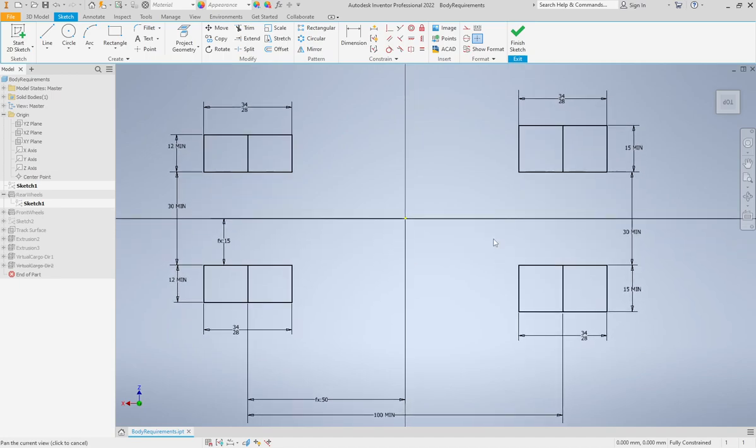Now there's a couple of new dimensions in here. From the inside face of my 2 front wheels, that is the most inside face of the rotating part of the wheel that does not include the axle. If you have a bearing that sticks out that's part of the wheel, so glued into or fixed into the wheel, that would be the most inside face. So be careful about this. It's not necessarily the edge of the wheel. When you take the whole rotating component minus the axle, we're looking for the most inside face of that.